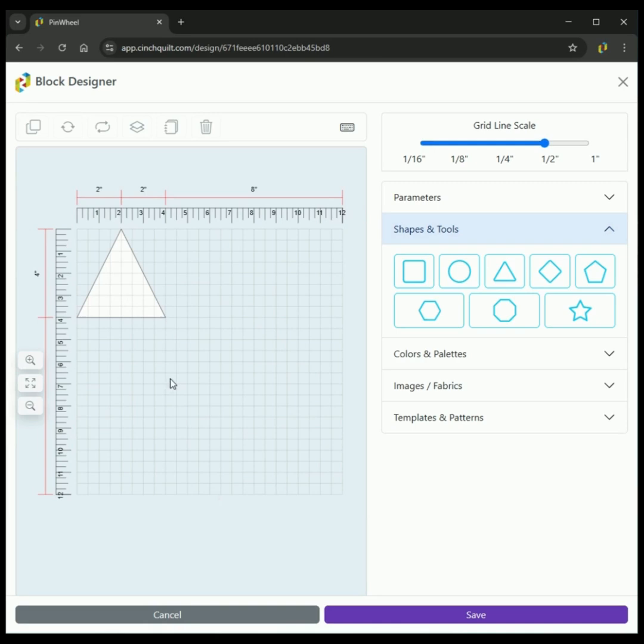In this case, I want to create a windmill pattern. So starting with this, if I click on this patch, I get this bounding box. Just by one click on it, it is giving me this bounding box. This allows me to stretch or skew that triangle, but it does it proportionately. It's keeping the same look, the same orientation, where it's skinny towards the top and then fatter, wider towards the bottom. It's allowing me to scale that. But most of the time, I'm going to need to do something slightly different. Maybe I don't want this orientation. Maybe I want something slightly different.